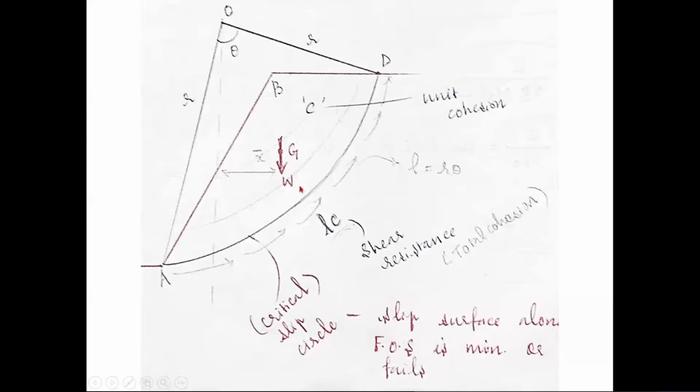Can you see these light lines? And this is another dark line that I have drawn here. These two light lines also I have drawn here. So I don't know where this slope is going to fail. I just don't know. So I have this slope here, I have this face of the slope here, and I know that this soil is cohesive. This is my only information that I have. So what I'm going to do is find out for what weight of this soil wedge this whole condition is going to surpass the equilibrium of the slope. That is what I'm going to find out.